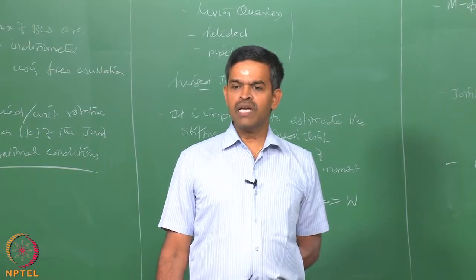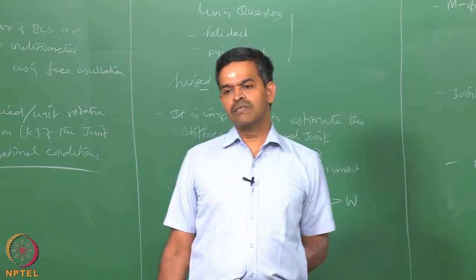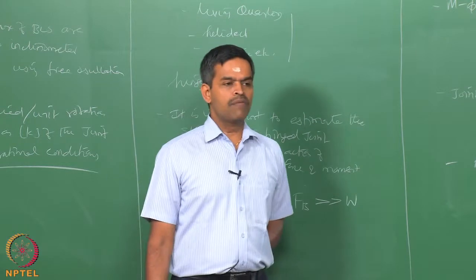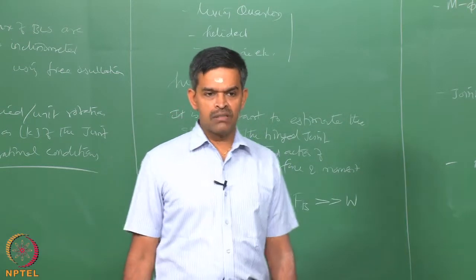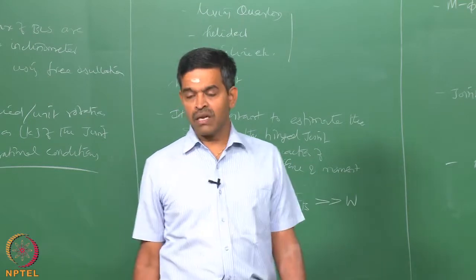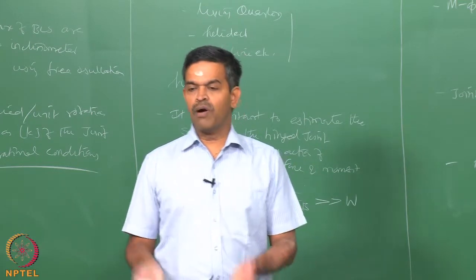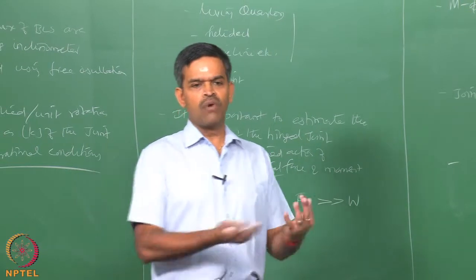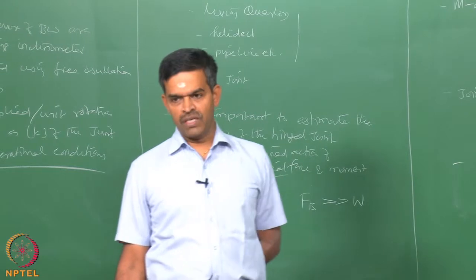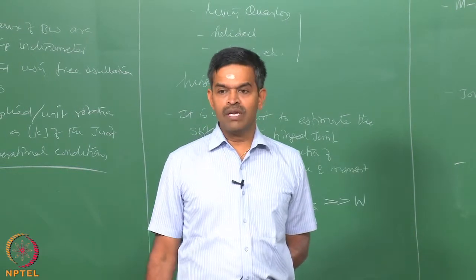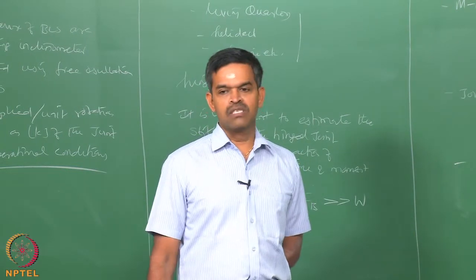So, estimates of the moment characteristics or the stiffness properties of the hinged joints in the uninstalled condition will not help in this case, because systems like Triceratops are essentially positively buoyant. Therefore, when they are freely floating, the hinged joint will not depict the actual behavior of the stiffness that it is supposed to show when it is loaded or commissioned on the sea bed.